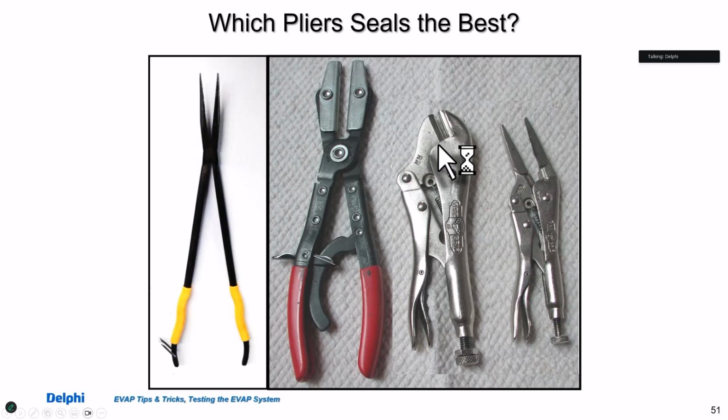This is a fuel line hose clamp that OTC made. I've used those. The problem is sometimes they're not wide enough for some of the hoses we need. Vice grips, you say, oh, I can't use vice grips, I'm going to damage something. Well, first of all, rule of thumb is never clamp plastic lines. Okay, not a good idea because they don't go back to their original condition.